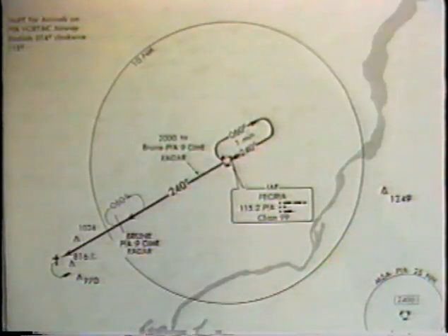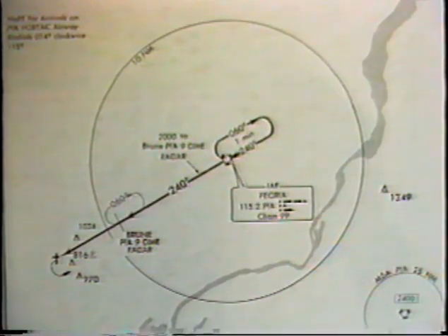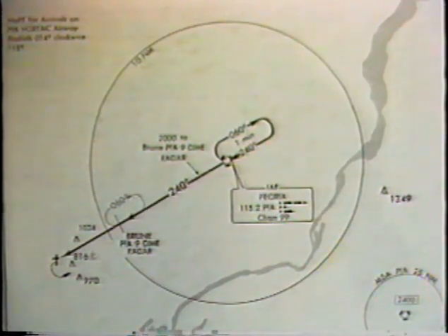Here we see a VOR approach with a holding pattern in lieu of a procedure turn. The holding pattern maneuver is also mandatory, and the pilot is expected to make an appropriate entry to the depicted pattern. The minimum required number of turns in the hold is 1, including the entry. That is, cross the fix twice, once outbound and once inbound.